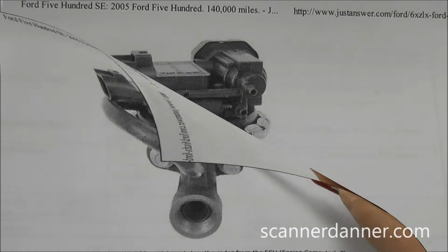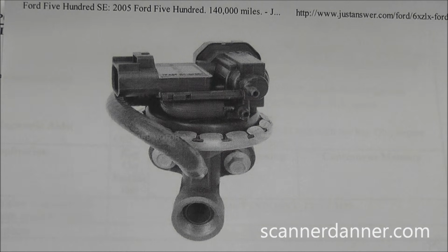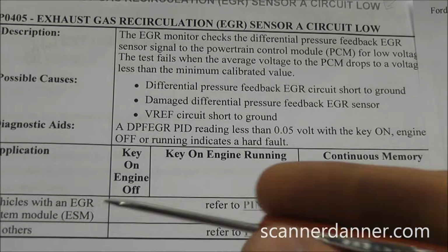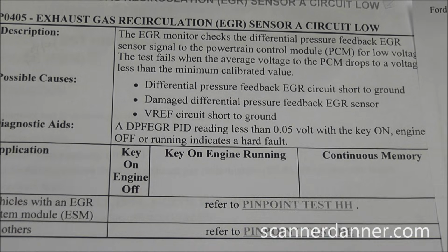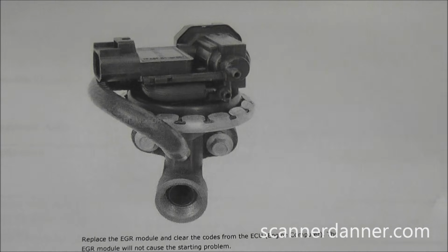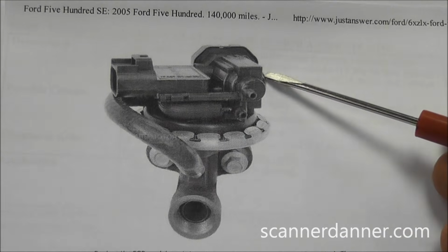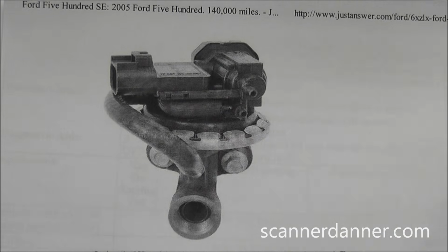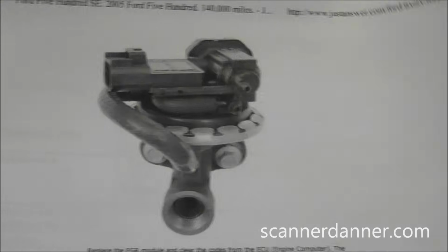So all we really need to do to know if this has the EGR, what this flowchart is calling the EGR system module, which is again this device, all we need to do is do a visual inspection of our EGR valve and see what design we have, and then we'll know which flowchart to follow.